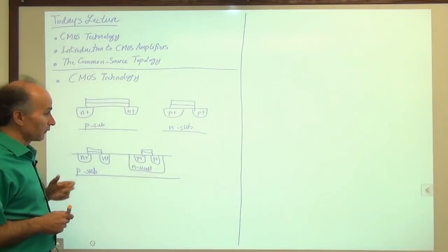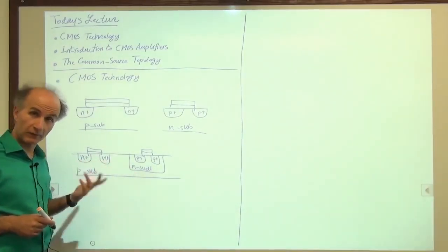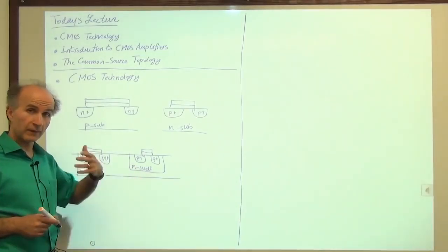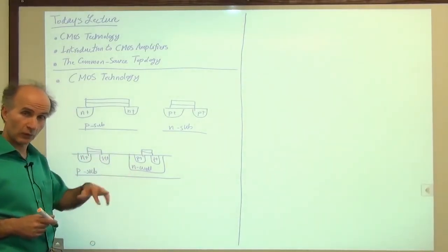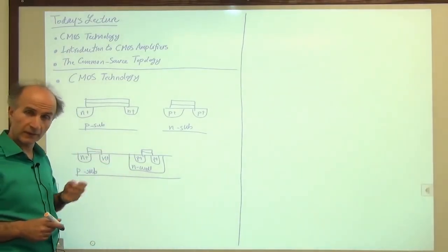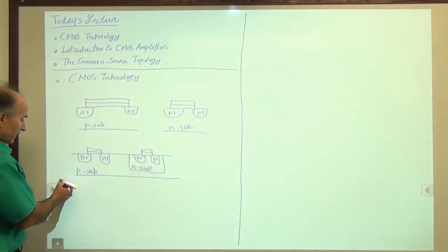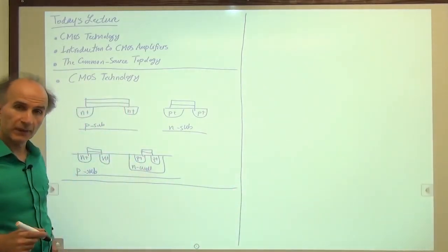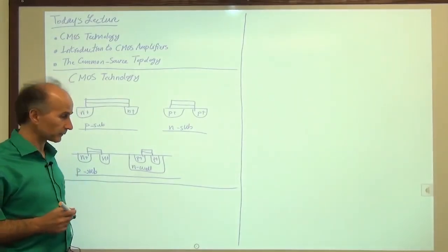All right. If you have taken digital circuits using MOS devices, you have seen, for example, the CMOS inverter, which relies on NMOS and PMOS devices. In fact, most static logic circuits that use MOS devices rely on both NMOS and PMOS. If you take the PMOS away, it's a very difficult design, a very power-hungry design. All right. So that is CMOS technology, and now we have access to both of these, and that's how our designs will proceed. Sometimes we use NMOS, sometimes we use PMOS, sometimes we use both, so we will see those.